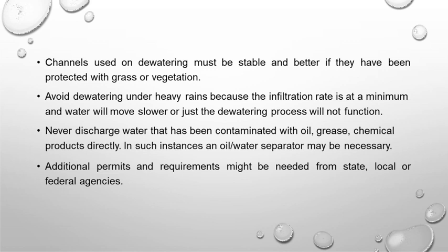Okay, so the reciprocating pump is driven by power available from an external source. This movement of the piston creates alternating vacuum pressure and positive pressure in the cylinder, which raises the water. Okay, so first, if water acts only on one side of the piston, the pump is known as a single acting pump.